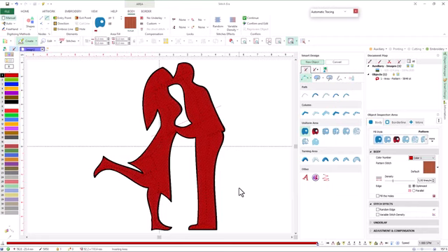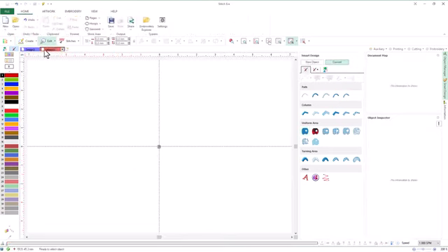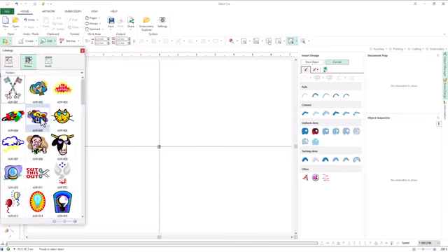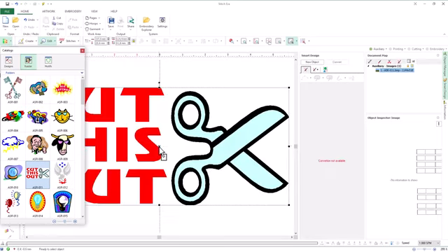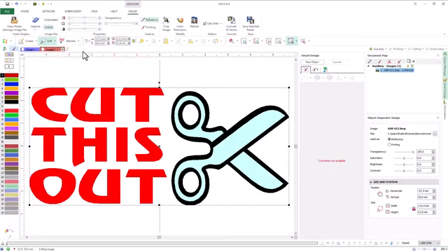So, let's create another new design and try with another image to explore the tool further. We will select an image that allows us to use auto trace with turning areas. Using the rescale command, we will adjust the size so that these segments become about 7 mm width.